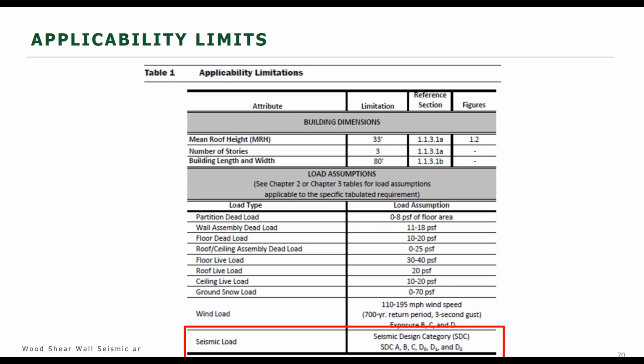So the IRC breaks it down even further so that it can fine-tune the seismic design when it looks at the residential design of a building. And this makes sense when you think about it. For example, if you're designing for tract housing, you're designing for one building that's used multiple times within a tract, you really want to fine-tune your calculations and reduce some of the cost on that one design that could be used multiple times. So that's one reason.